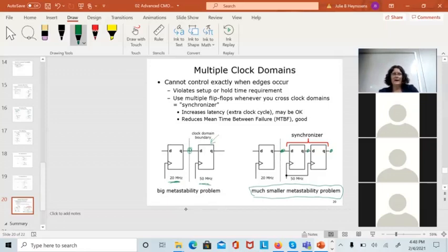It is so bad by the time you get to DDR6 that the data's coming out so fast they are deciding what the data is before the output has had time to settle. And what they do is they look back at the 4 previous values of the data.